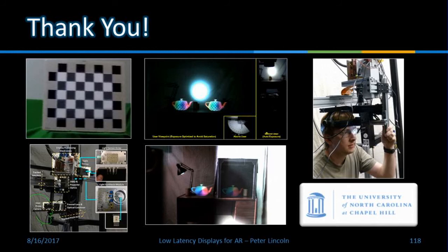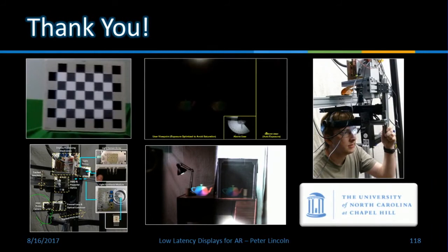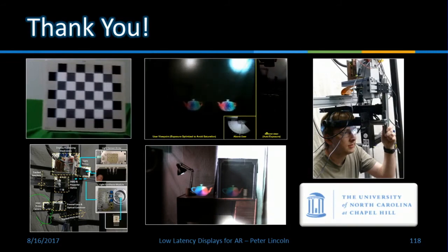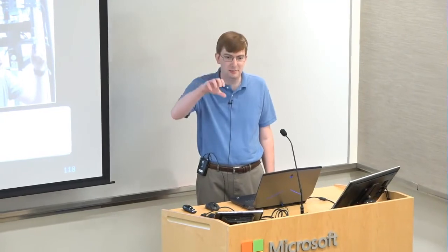So if you were going to build a VR type display, would you still use these digital mirror devices? For see-through, the issue with these DMDs is the bulkiness, because you've got the DMD and some sort of lens system on it and so forth. Now, there are OLED displays that can be operated in a binary fashion at 1 kilohertz.